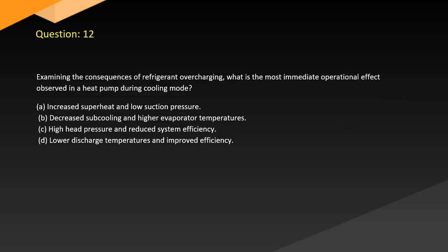Question 12. Examining the consequences of refrigerant overcharging, what is the most immediate operational effect observed in a heat pump during cooling mode? A. Increased superheat and low suction pressure. B. Decreased subcooling and higher evaporator temperatures. C. High head pressure and reduced system efficiency. D. Lower discharge temperatures and improved efficiency.